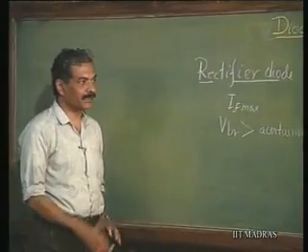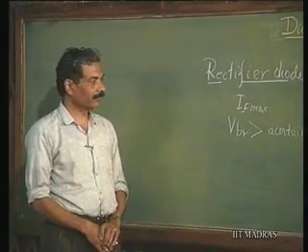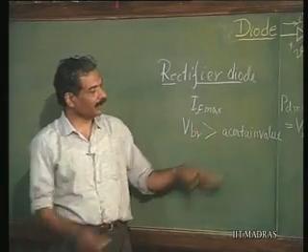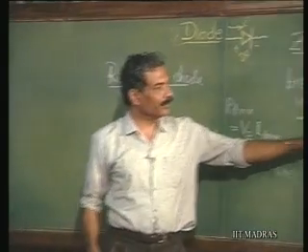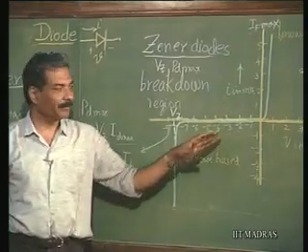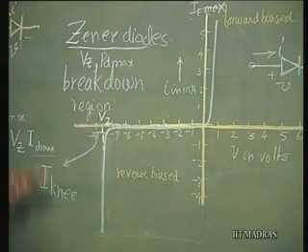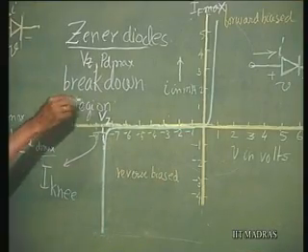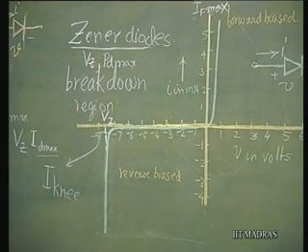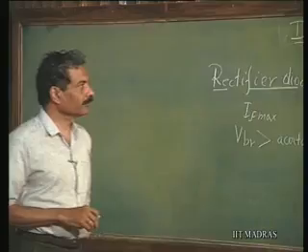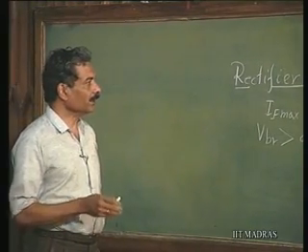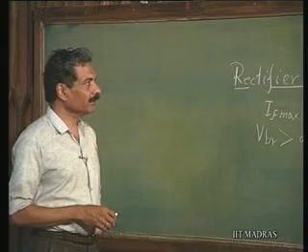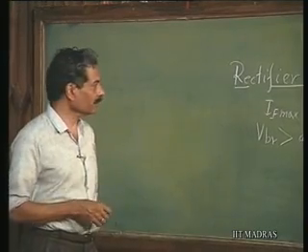These are the specifications for the Zener diode. The breakdown here has to be greater than a certain value, up to which you are going to use these forward bias and reverse bias voltages, whereas in the Zener case it is the breakdown voltage which is important, it is specifically and accurately mentioned in the specification. So, let us see what are the equivalent circuits for these and where are the applications of this.